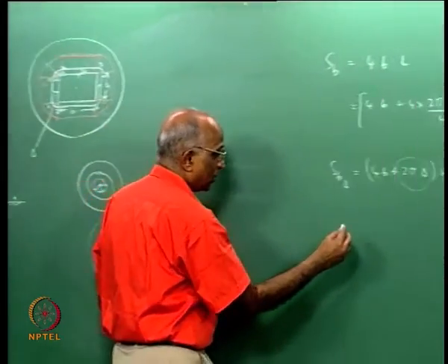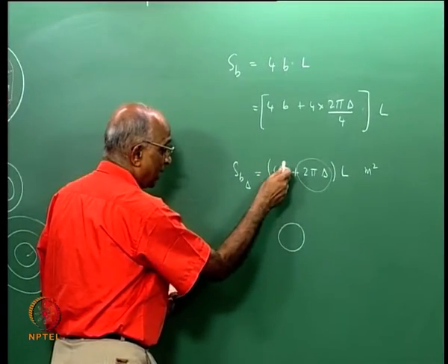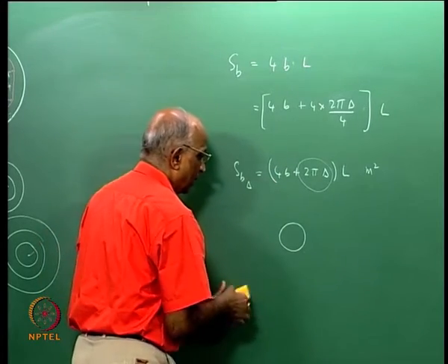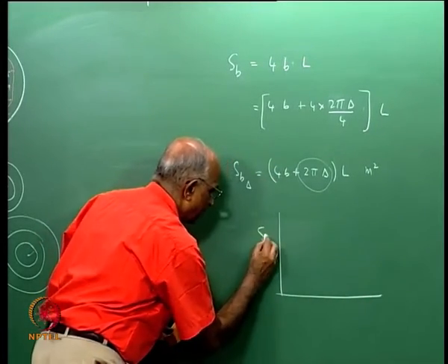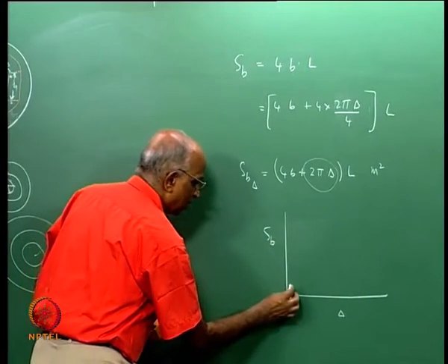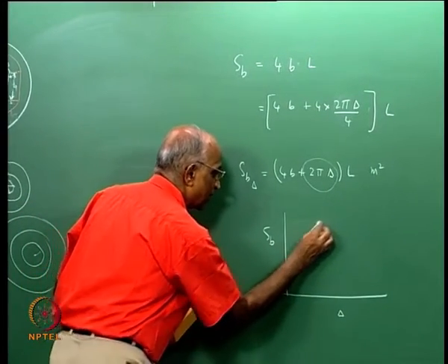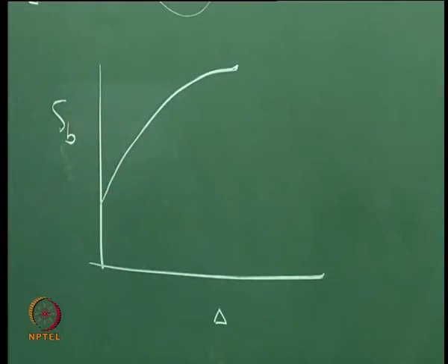Rather than a grain with something like a circular hole, where the diameter directly increases, in this case I get little effect over here, and the burning surface area would keep on increasing still further as the value of delta keeps increasing, until it reaches this limit. When does it reach the limit?